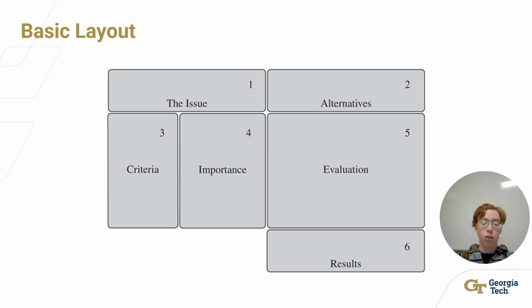The third step is to select the different criteria for comparison. These are engineering requirements that are ultimately derived from the customer requirements. The fourth step is to develop the relative important weighting of these criteria. The fifth step is to evaluate all the alternatives in terms of how well they satisfy the criteria. The sixth step is to compute the overall satisfaction and pick the best concept.